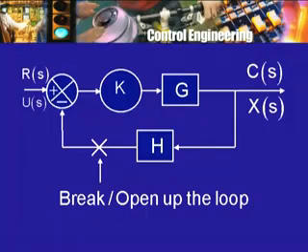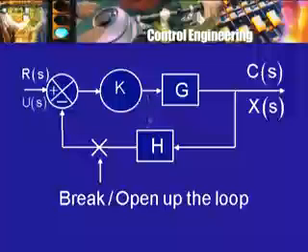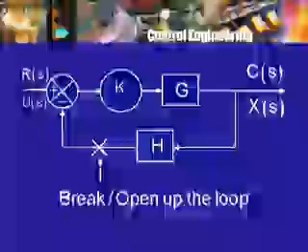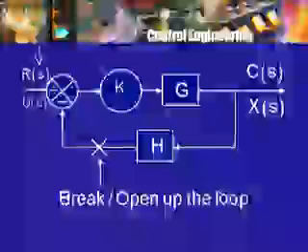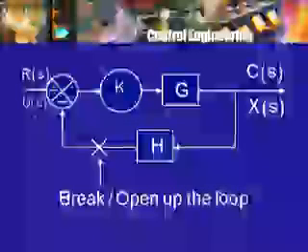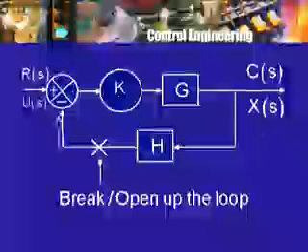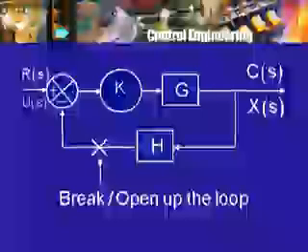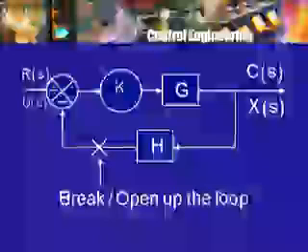How? I am to look at the transfer function GH. Now where does the transfer function GH come about? Now if you remember, we had this G in the forward path, then the gain K in the forward path, then we had H in the feedback loop, and this was the configuration. With this difference device, R of s here, C of s, or for us now I am using U of s and X of s, and here is the feedback path. Now if I want to measure GH j omega for various frequencies, how do I get it from this?